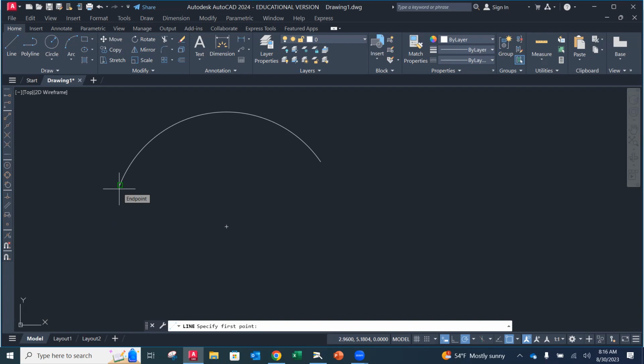And if that's the case, the geometry that I create, if it is not a continuous path that meets cleanly at corners and has the radiuses trimmed properly, and if there are overlaps or they're not meeting, it can't read that toolpath. Now, either you have to go back in and correct those things, or the person that is running the machine has to correct it.